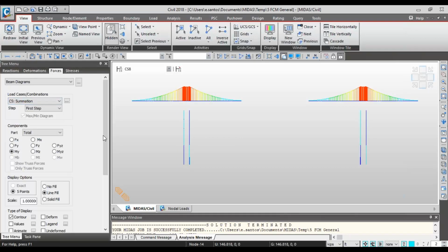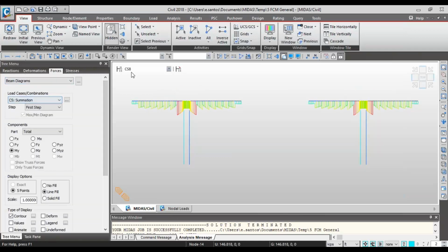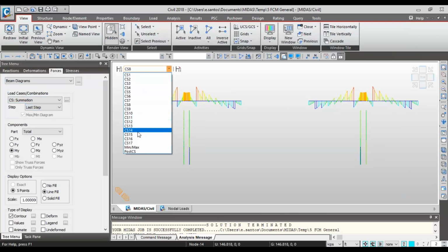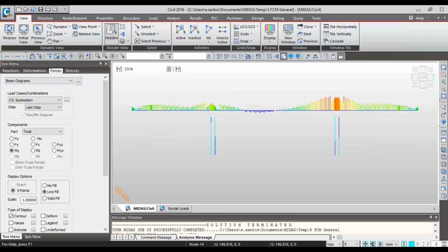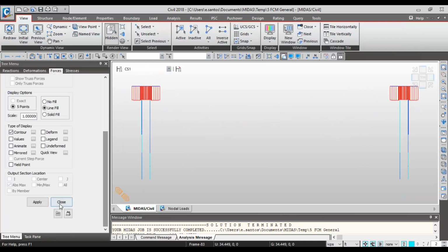If you want to get a summation, which will include the pre-stressing, tendons, creep, shrinkage, and compressive strength, you can also use this option for summation. First, last stage, and you can see how the bridge closes from one stage to the other. That would be another option.